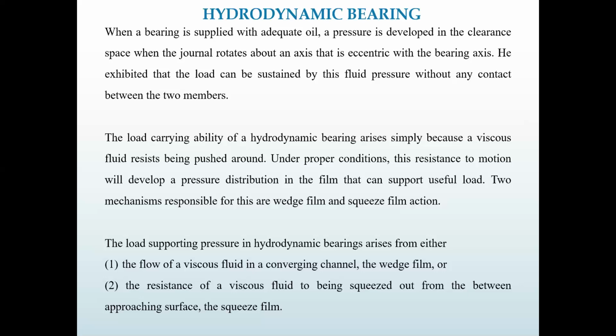The load supporting pressure in a hydrodynamic journal bearing arises from the flow of viscous fluid in a converging channel, or wedge film, and the resistance of viscous fluid to being squeezed out from between approaching surfaces, which is called the squeeze film.